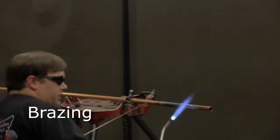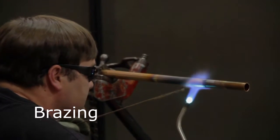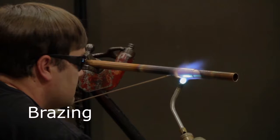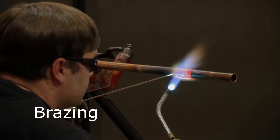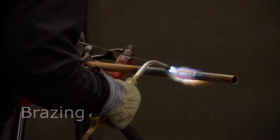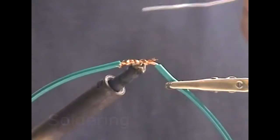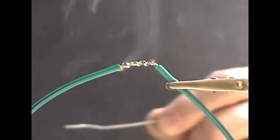During the brazing process, a filler metal is melted and distributed between multiple solid metal components after the metals being joined have been heated. The filler metal must have a melting point that is above 840 degrees Fahrenheit, but below the melting point of the base metals. The metals joined in brazing must also have high fluidity and wettability. Soldering is similar to brazing, the only real difference being that in soldering, the melting point of the filler metal is below 840 degrees Fahrenheit.